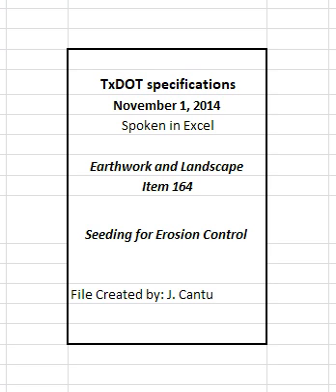4. Measurement. This item will be measured by the square yard or by the acre. 5. Payment. The work performed and the materials furnished in accordance with this item and measured as provided under Measurement will be paid for at the unit price bid for broadcast seeding, perm, of the rural or urban seed mixture and sandy or clay soil specified, broadcast seeding, temp, of warm or cool season specified, straw or hay mulch seeding, perm, of the rural or urban seed mixture and sandy or clay soil specified, straw or hay mulch seeding, temp, of warm or cool season specified.